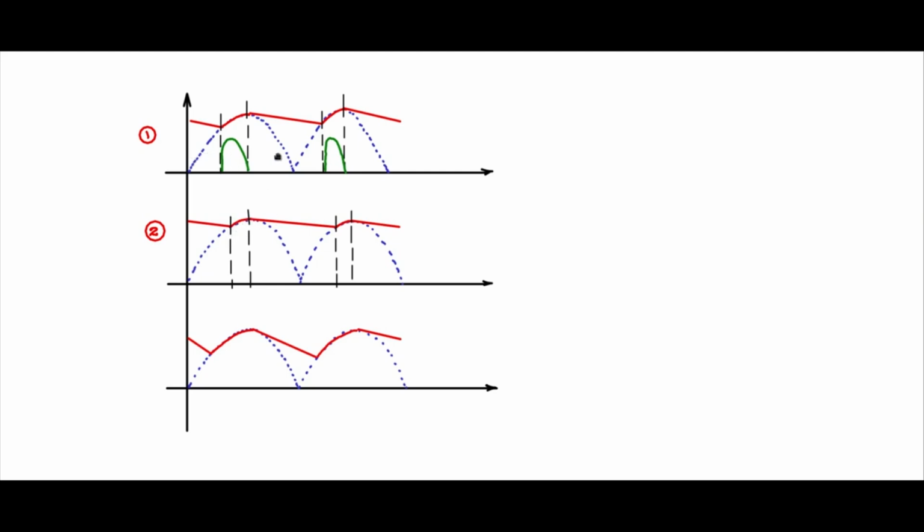Now let us say in case 1 some amount of power is being delivered, and let us say this is P load. Consider the same average power delivered to the load, you will find that the current conduction, as it is narrowed in order to keep the same area, you will have a much higher value of peak. Current peak will be much larger compared to this.